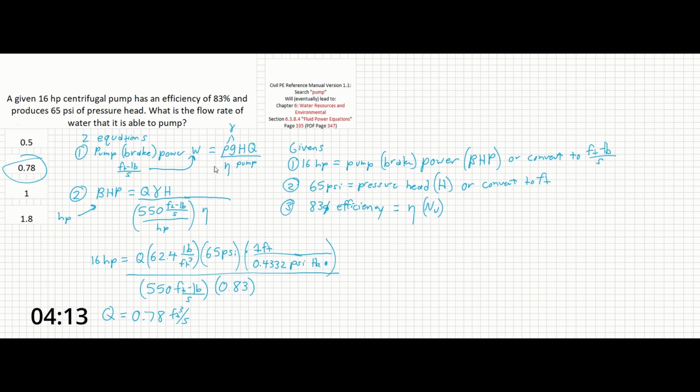In summary, this problem mostly requires you to do some unit conversions and know where some terms are so that everything in the fluid power equation cancels out. It'll also save you some time if you can recall the density of water, or at least know where to find it on page 2, because otherwise you won't be able to solve the problem. And that's it.